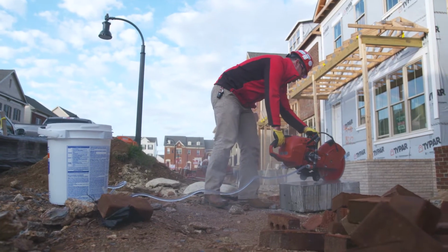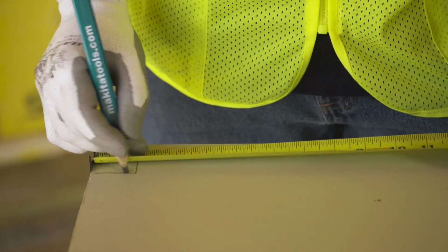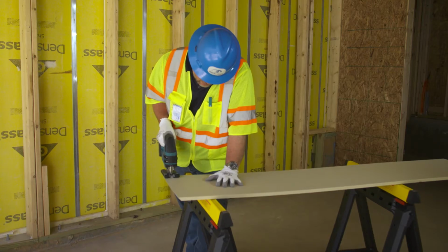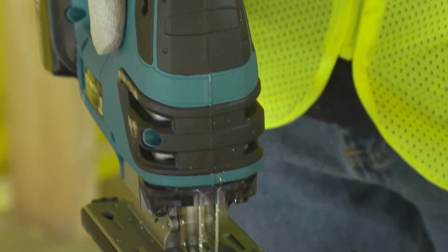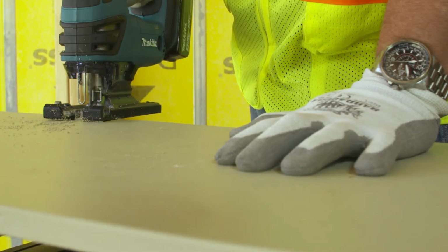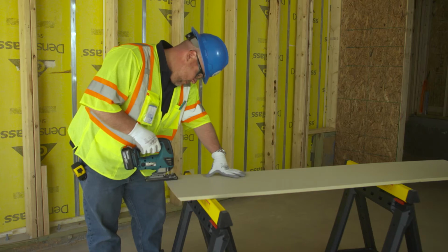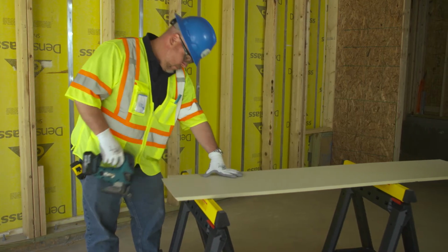Flying debris and particles are other hazards involved with saw cutting. Debris can be thrown while cutting and can include wood chips, splinters, and broken off saw teeth in pieces. Remove any broken or cracked saw blade from service immediately and maintain sharpness of your blade. And always wear proper eye and face protection.